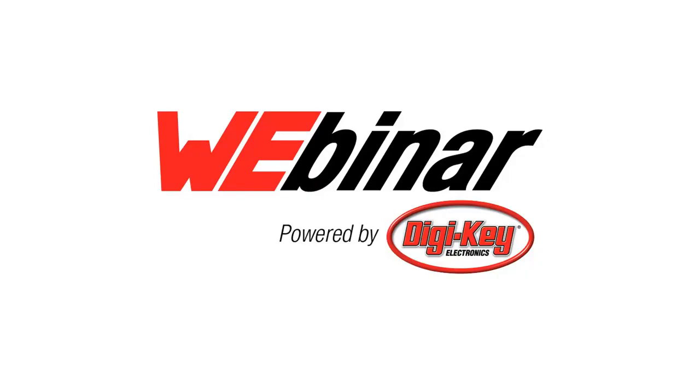Yeah, that's a great question. I'm always a little nervous plugging my phone into USB ports at the airport as well. But the actual negotiation for the power delivery happens over the CC lines. To go into a little more detail, the cable gets inserted, and we're able to detect the orientation of the cable on those CC lines based on the pull-up. But then there's a modulation scheme that happens between the source and the sink, and that negotiation happens over the CC lines themselves.